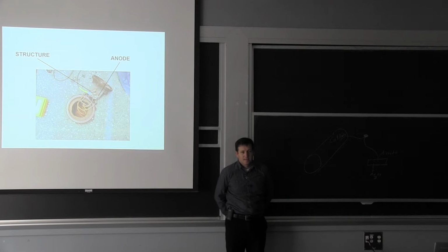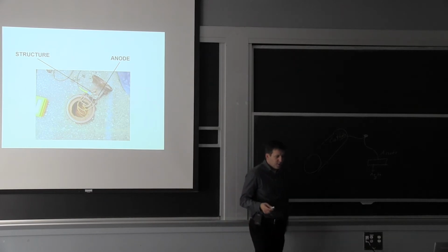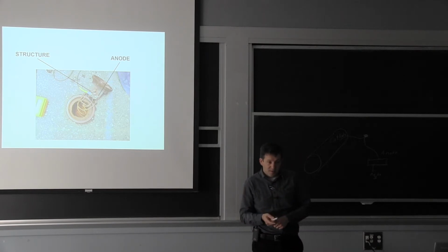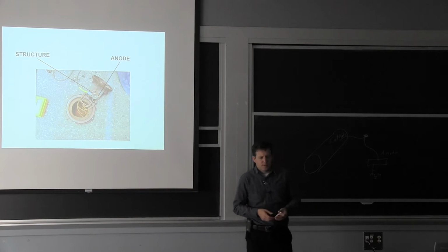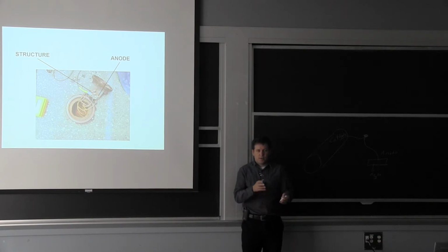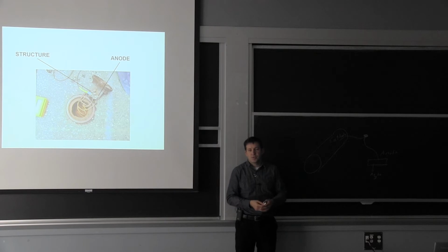Yes. How do you decide how far to put it from the tank? If you are a corrosion engineer, you have to go and test the soil resistivity, and you have also other testing for how corrosive it is, and that's how you size your system. But the bulk numbers I gave you, like 10 feet, a lot of times they do the soil test, but they don't necessarily change the layout so much because they know the soil is going to change, so they try to be a little conservative in the numbers that they're going to put in.